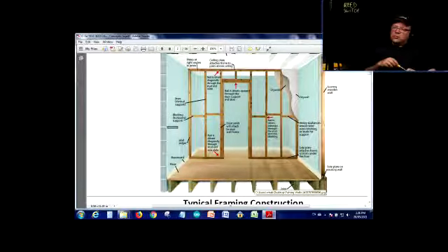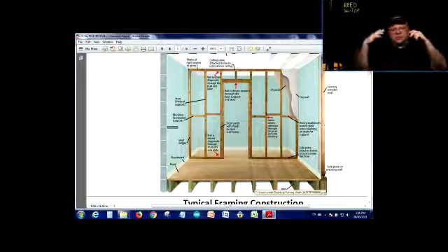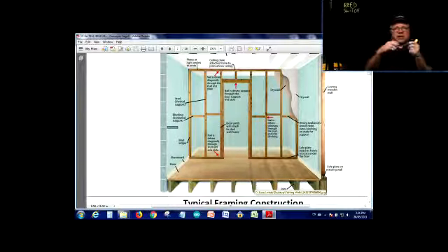You're always going to want the possibility of adding more wires if you need to add an outlet or a device, or something else comes on the market that needs some installation. So when it comes to a basement ceiling, it is always better in this 21st century to install what's called a drop ceiling, which involves a metal grid, and on that metal grid you insert ceiling tiles.